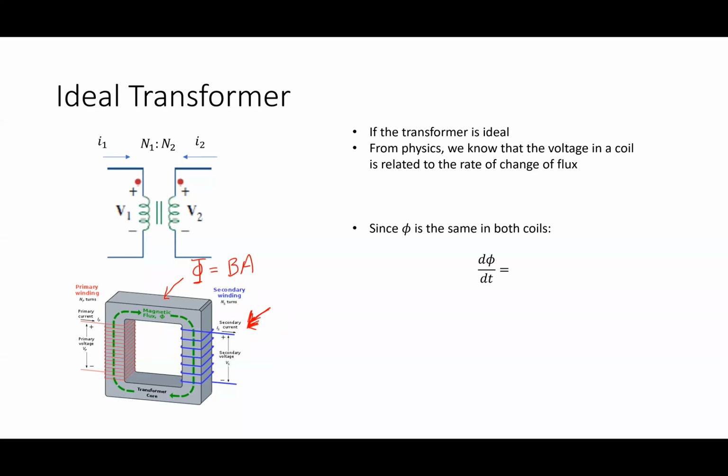Well, 6 times the total amount going through that transformer. Because I have flux going through one coil, and that's the flux phi. And then I have flux going through another coil, and that's the flux phi. And flux going through another coil, and I add those coils all up because they're all connected in series with each other. So if I looked at one coil, the voltage on one coil is basically d phi by dt.